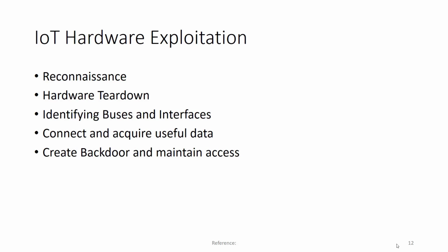Next comes the hardware teardown, where we open a device by bypassing the hardware protection, or we can say we break the device to open the components of the device, chipset, and board. Once we open the device board, we need to look for the chipsets, components, buses, and interfaces on the board of the device.